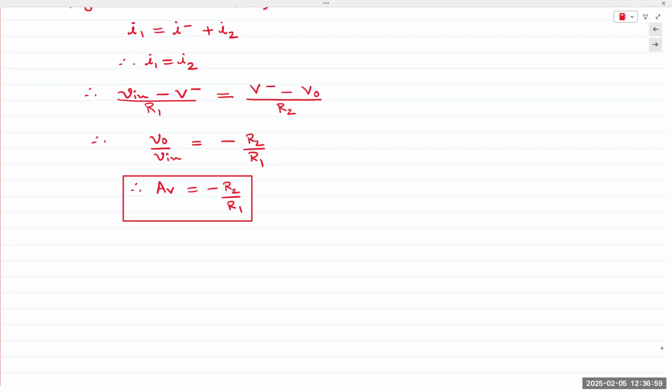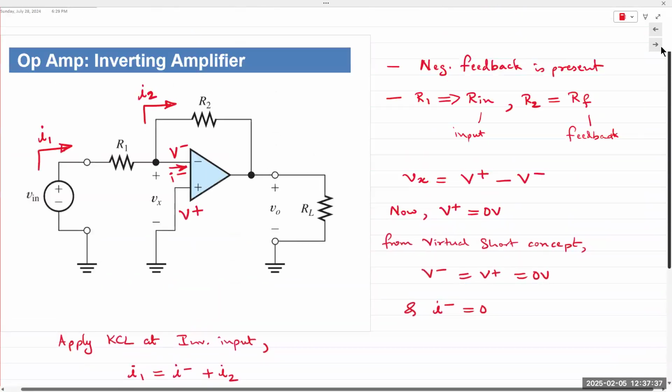If you apply 10 volts at the output, you get, how much would you get? No, if it's a gain of 10 and you apply 10 volts at the input, what would be the output? 100. If you apply 100 volts, how much would you get? Okay, technically that answer is correct, but where is that energy coming from? I'm asking everyone. It comes from the power supply voltages.